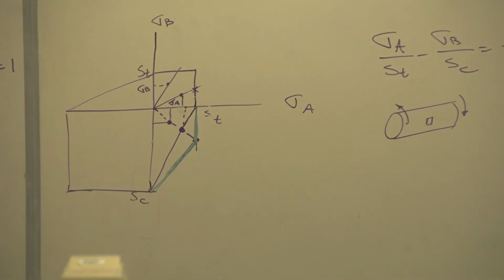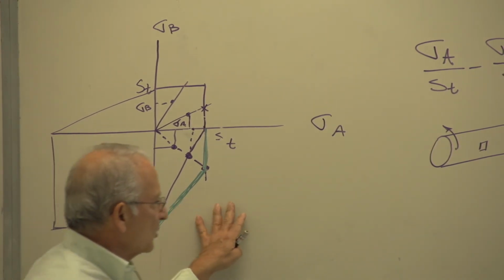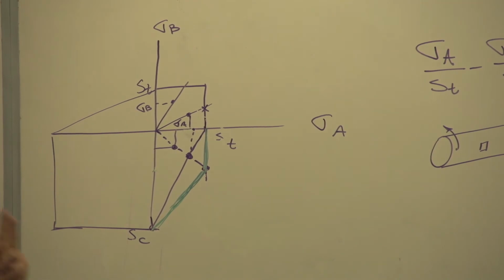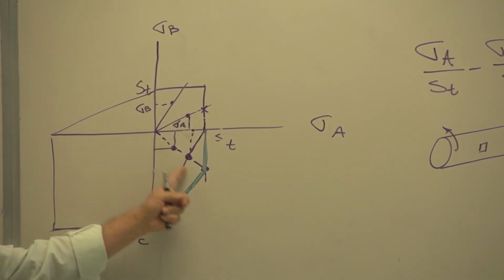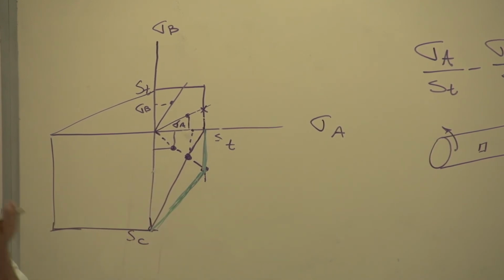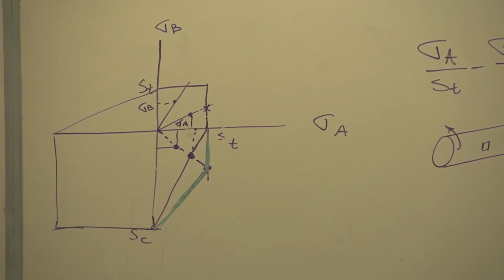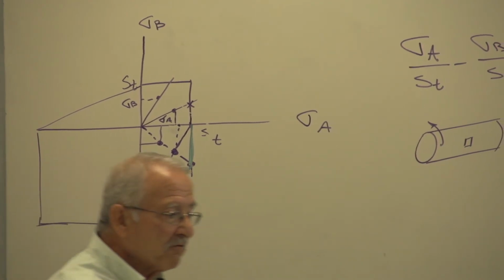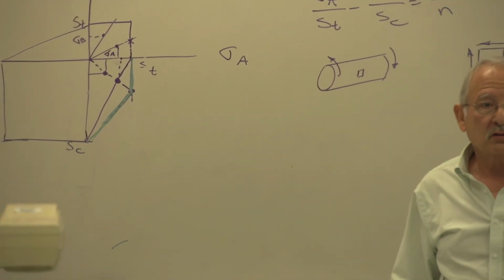In all cases, regardless of the type of failure theory that you're using, you have to consider two things: strength and stress. Load line, strength line. Wherever they cross, that's failure. Factor of safety would be the ratio that you have left before you get to a point where they cross.